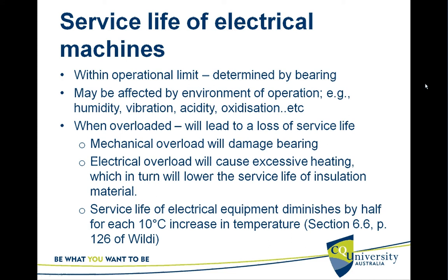Regarding service life of electrical equipment, the standard acceptance is that it diminishes by half for each 10-degree increase in temperature. So that gives you a good idea about the impact of excessive temperature on the machine. That happens because of the degradation of the insulation of the windings, mainly in case of electrical machines.